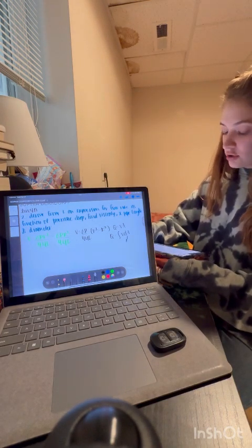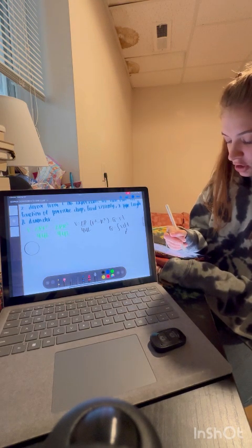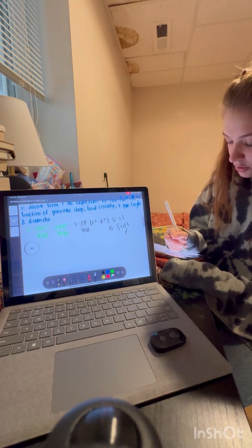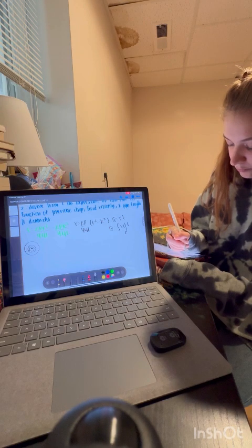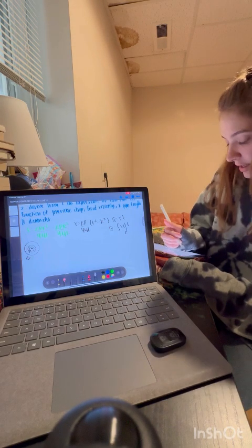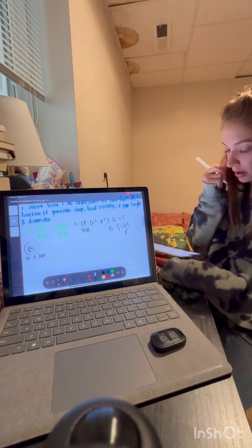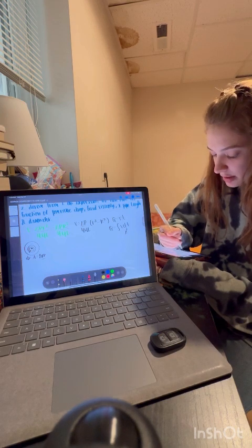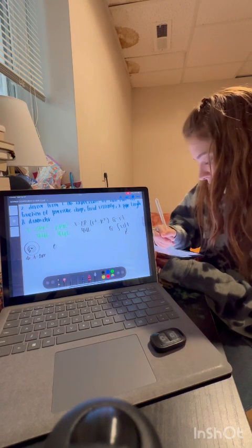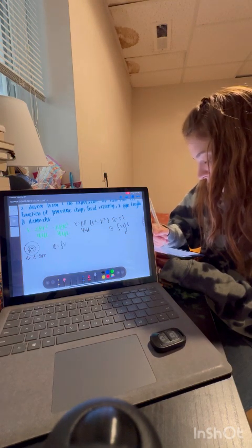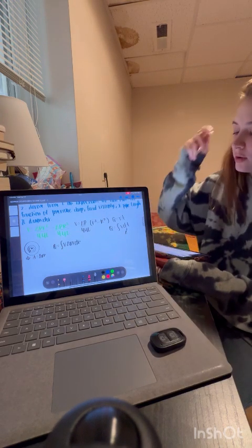Breaking down our differential area, if you cut a section of our pipe, here's our center, and if you were to make rings in this, we identify this as dr and the area as 2 pi r. So Q is equal to V times 2 pi r with respect to a differential radius.